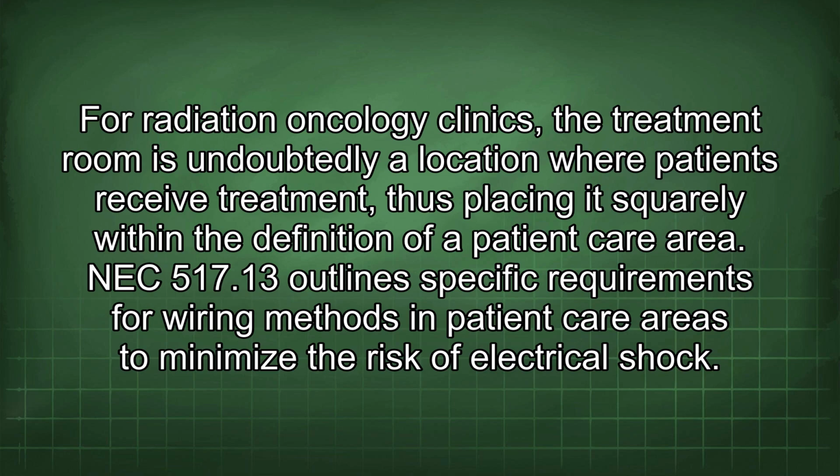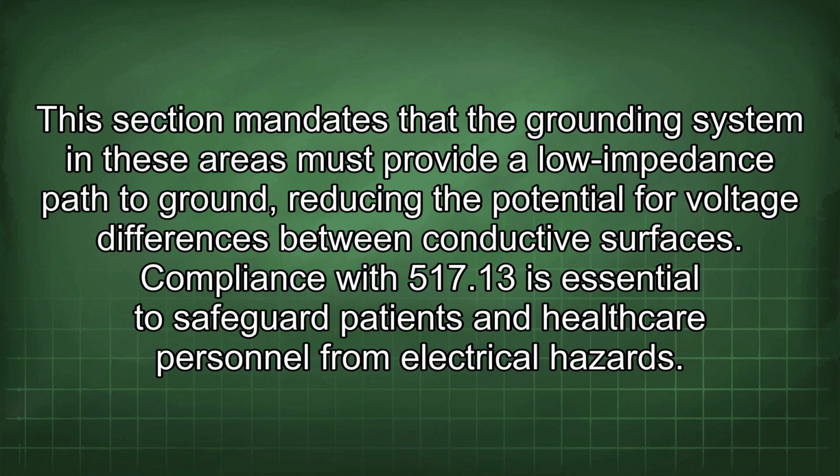NEC 517.13 outlines specific requirements for wiring methods in patient care areas to minimize the risk of electrical shock. This section mandates that the grounding system in these areas must provide a low impedance path to ground, reducing the potential for voltage differences between conductive surfaces. Compliance with 517.13 is essential to safeguard patients and healthcare personnel from electrical hazards.